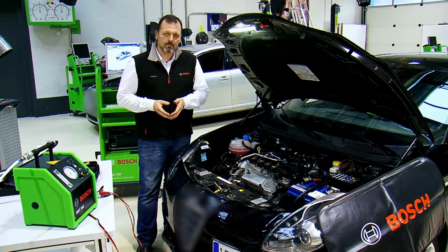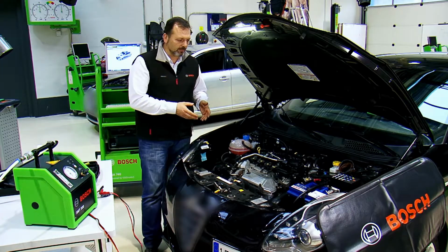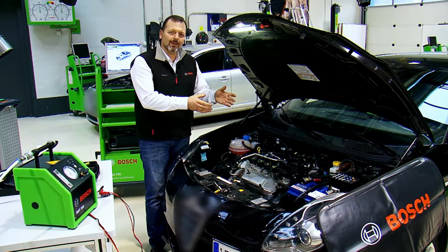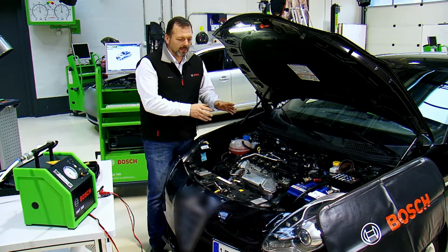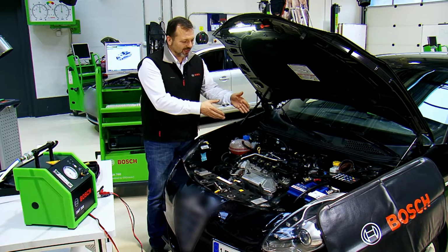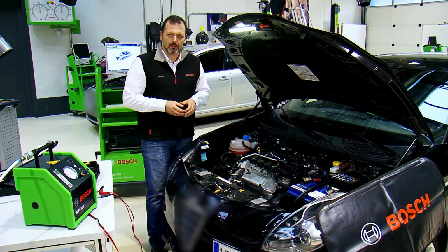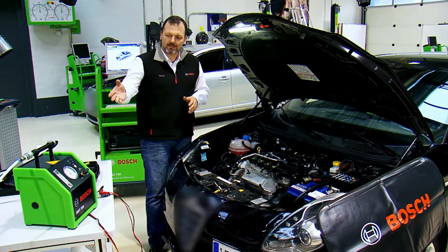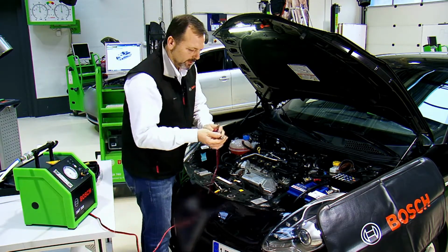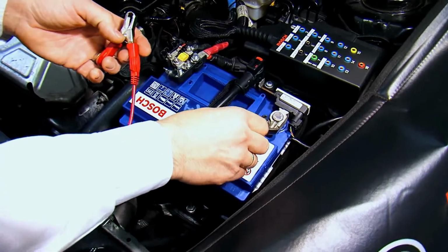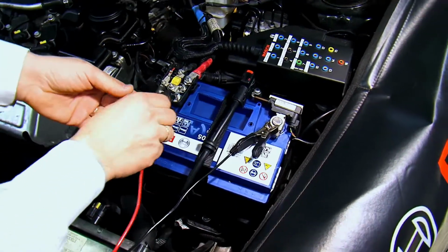Even by using the emission tester, we found out that the emission gas composition looks strange. On various occasions, the trouble had its origin in a leakage somewhere in the intake manifold area. To identify precisely the location of such a leakage on the engine block or intake manifold is very difficult and complicated. Now we try to localize the leakage with the SMT 300.